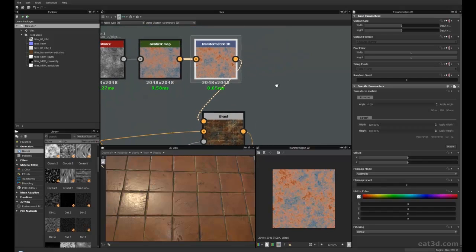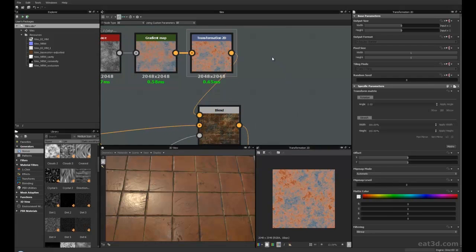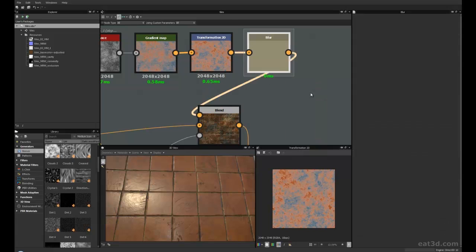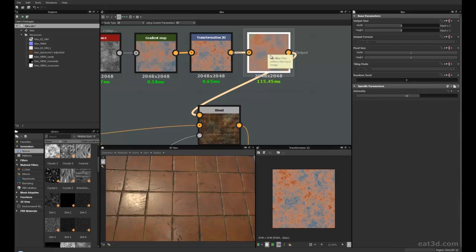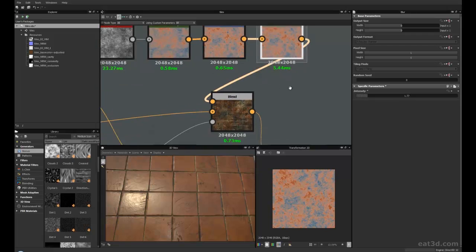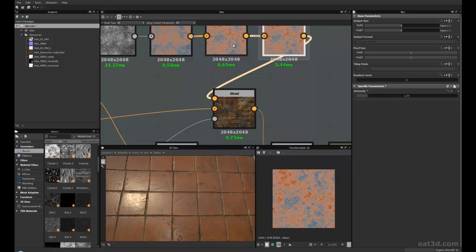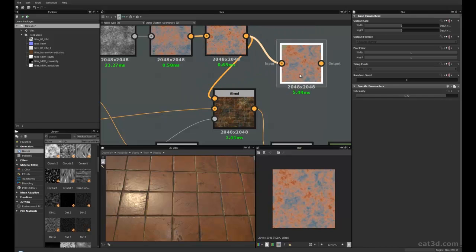If I wanted to blur that, if you select the actual node and press spacebar and then click a blur node, you can see it's made it really blurry. Or I can bring down the intensity of the blur, and we're pretty much back to where we were. That's another option you've got. If that fractal sum's a bit too sharp, you might want to blur it off a little bit. I'm not too fussed with that at the minute. I don't really need that one in there.